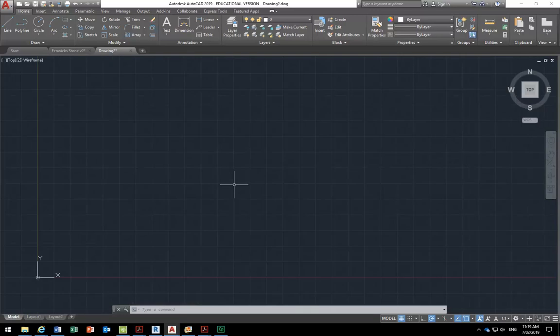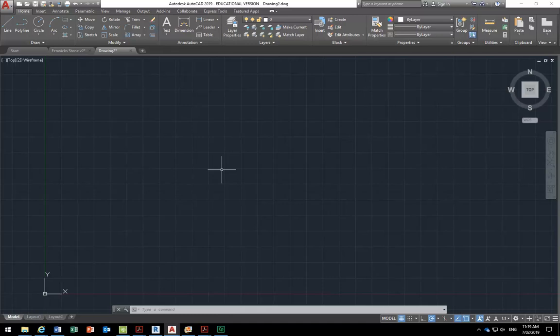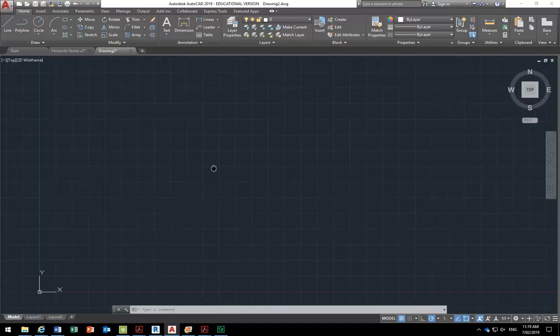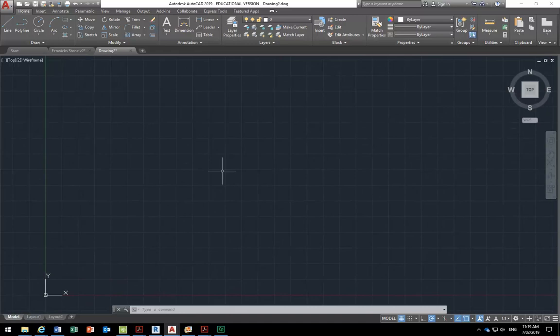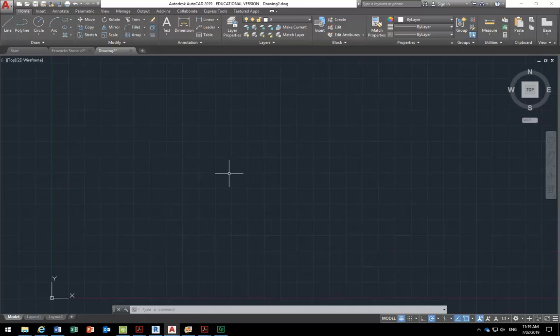Maybe? Hold it down? Yeah, exactly, hold the wheel down. And that's like SketchUp as well? Yeah, in SketchUp it's orbits, but then you use, I think it's Control to make it pan, or Shift, is it? Yeah, Shift to pan. Whereas in AutoCAD, holding the wheel down on its own pans, and then you use a modifier key. I always forget, Alt and Shift and Control. In AutoCAD, it's Shift to orbit. But yeah, hold it down to pan and roll it to zoom.